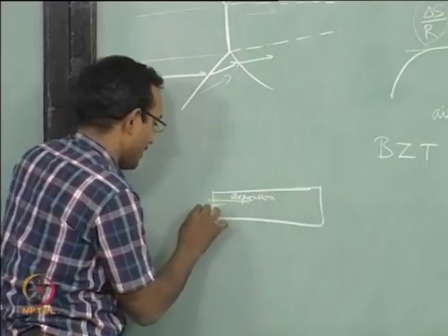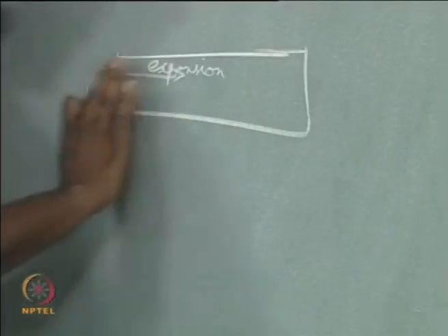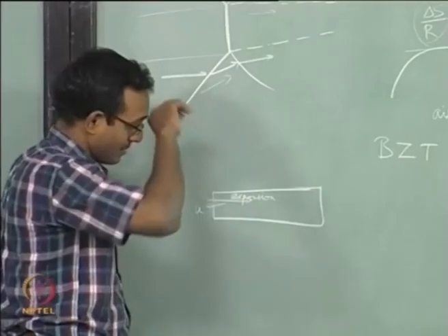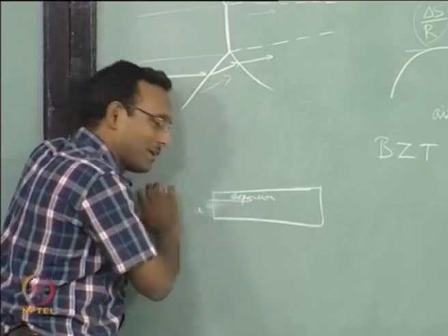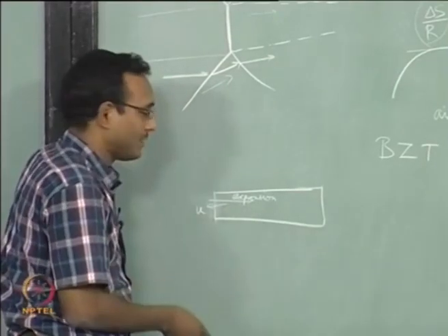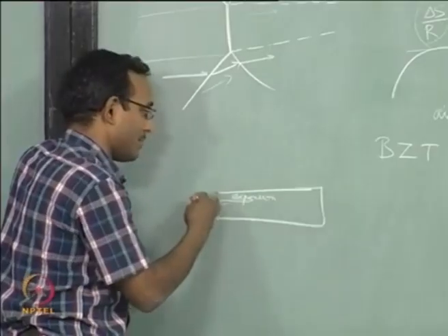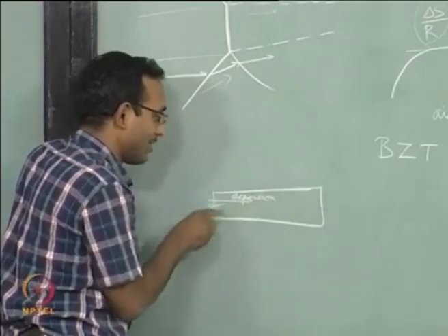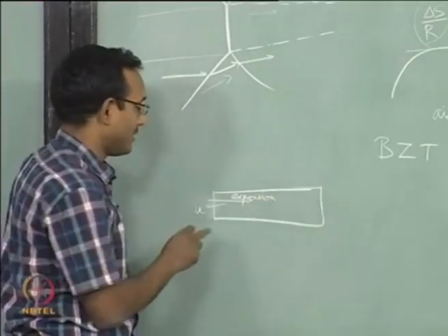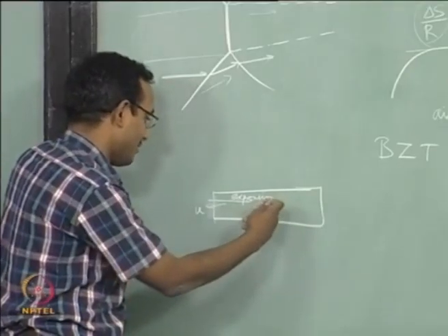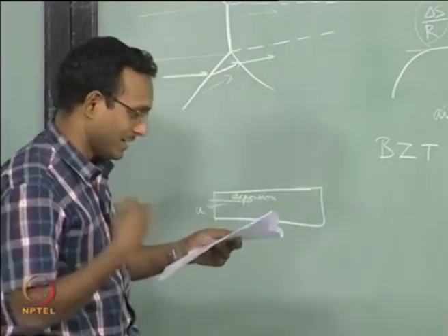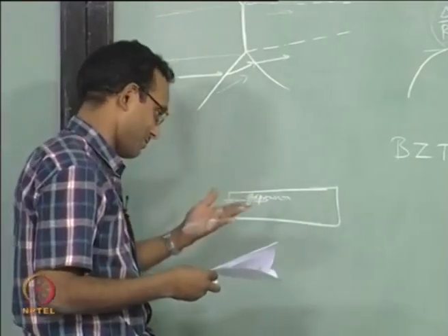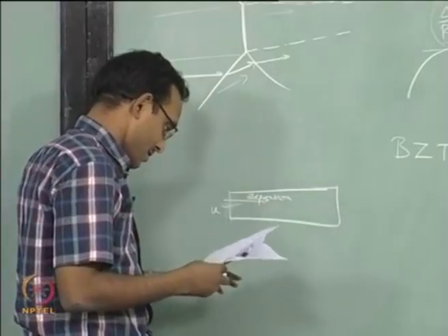Expansion goes that way while the velocity goes this way. Mass goes this way while the expansion wave goes that way. That is what you have to remember. Previously we said compression wave where there are more people dumped into the stadium and closed. Then they have to readjust, so there will be a compression wave going, all the people will go that way along with the compression wave. Expansion, if the wave goes to the right, the velocity induced by the wave is to the left. We already did this, I just want to reiterate it several times so it is easier for you to remember all this.